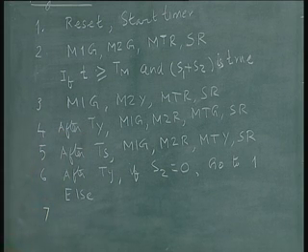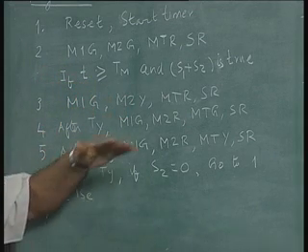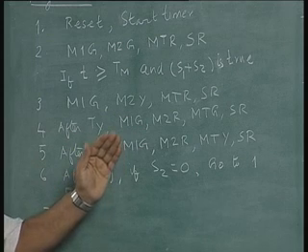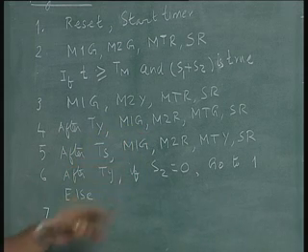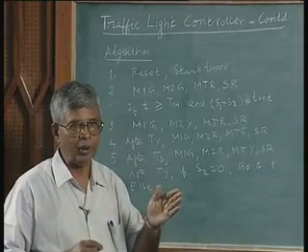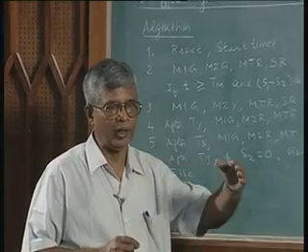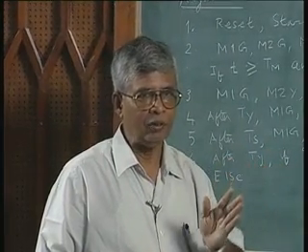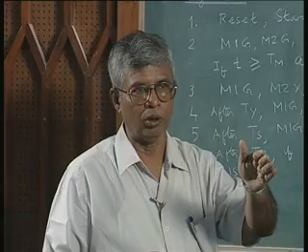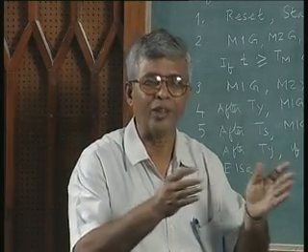stop the main road traffic on both sides, and then allow for the turning from the side to the main. In this case, what we specifically assumed was that the main road from left to right will be green when you allow the turning from the main road into the side road, whereas the same green from left to right will not be green when you allow the turn from the side road to the main road. That means the main road traffic should be stopped in both directions now.